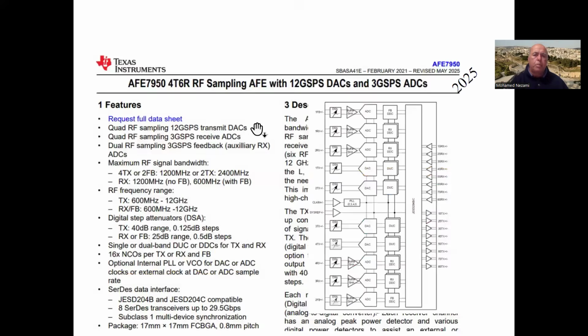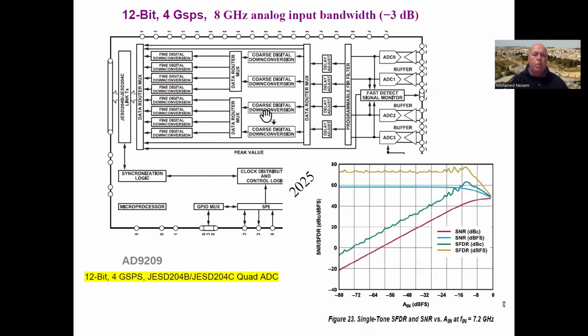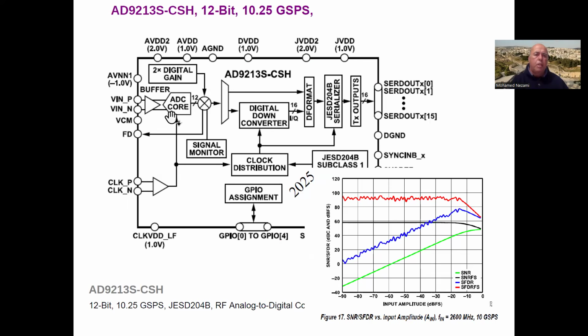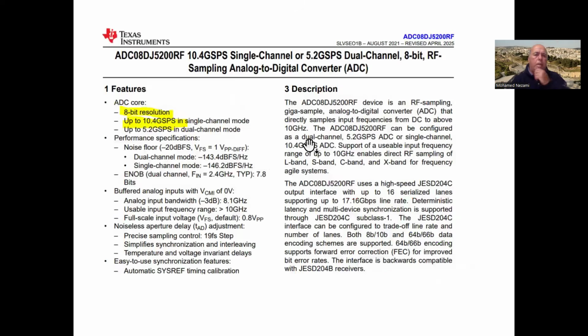There are some adjustments, tweaking buttons that you can have. Like in this one, for instance, you have an AGC digital gain. So you can actually scale and multiply by a constant or vary the signal level in the digital domain before it goes on to the air.